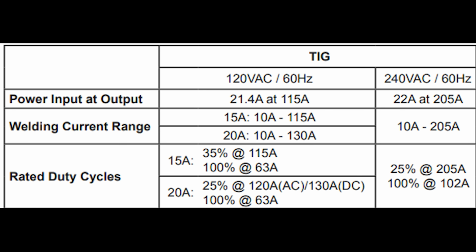And honestly, I think that's why they include a 17 size torch with most of these 200 amp TIG machines. The reason's simple: the torch will start melting and smoking, and it kind of gives you a warning, hey, let the torch cool off. Well, during the time the torch is cooling off, the welder is also cooling off, which allows you not to hit thermal overload.